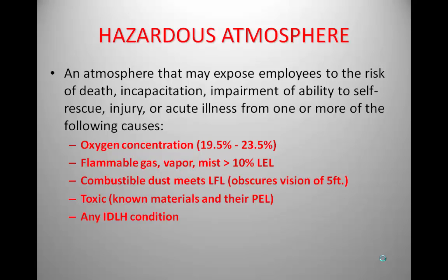So kind of get back on track with the 10% side. Let's say product X, that same product X has a LEL of 100. So at 10, your meter is going to go off an alarm. So it gives us that 90% window to make changes, whether we need to evacuate the space, figure out what's causing the sensor to go off, what's being introduced into the space to cause that.